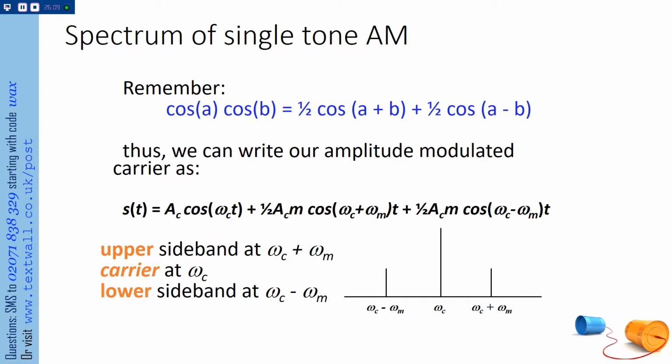If I were then to shift that over here, this is my bandpass spectrum. So the DC, harmless DC, 0 hertz, has now become FC, a carrier term. My signal, my sine wave, 5,000 hertz, has now become FC plus FM.